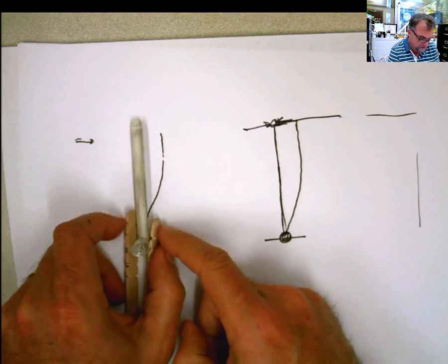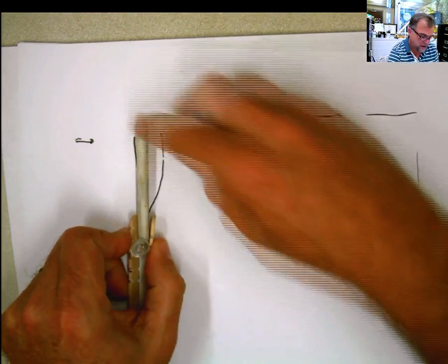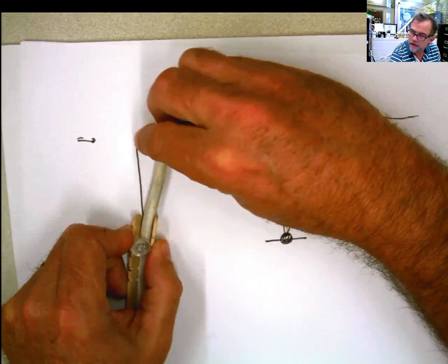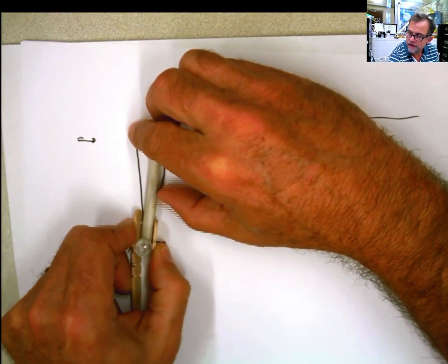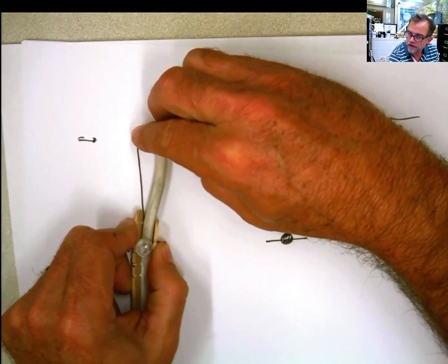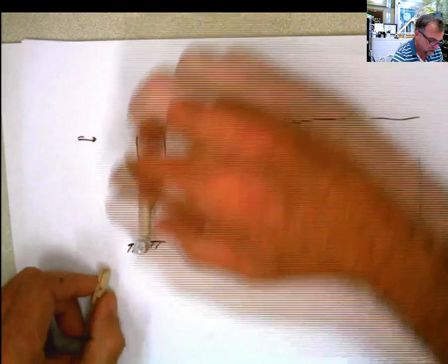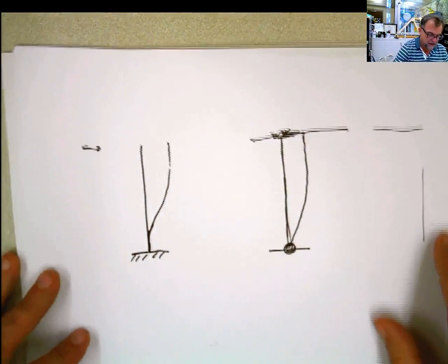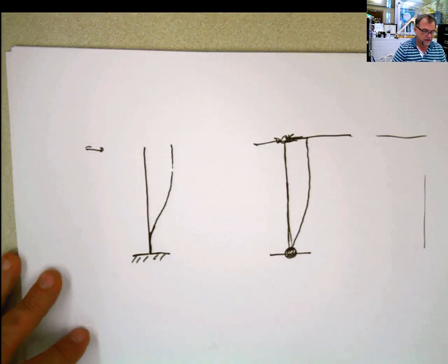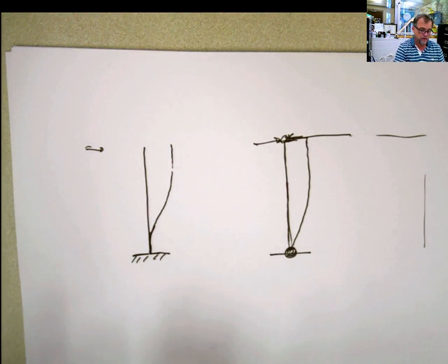Let's say that I fix these other parts here, and I apply the same thing. Now you can see the shape over there, you see? The shape starts from here fixed like that, no rotation, no deflection, no anything, and behaves like that. So if you know that, and if you can understand what that is, the method of the portal is really easy, because you can put the hinges wherever the inflection points are.